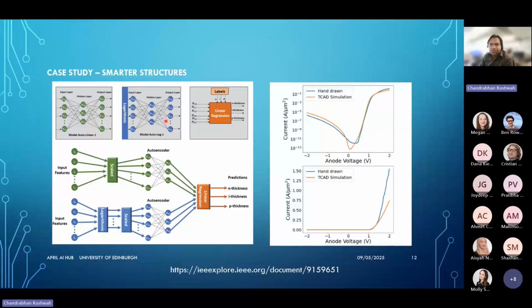In this study, the method is demonstrated using a PIN diode, where the goal is to infer variation in the layers and the thickness from the given current-voltage (IV) characteristics. While TCAD simulations can readily incorporate such variations for training data generation, conventional ML models tend to overfit sometimes, especially when unseen physical factors, hidden variables, affect the IV response in experimental scenarios.